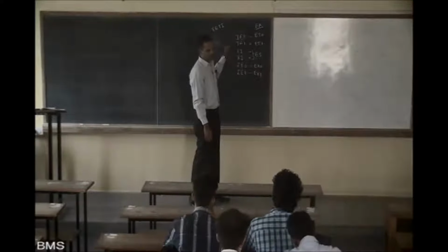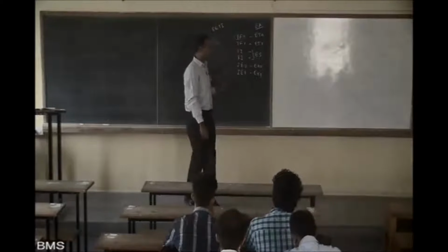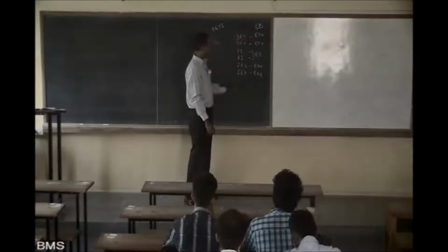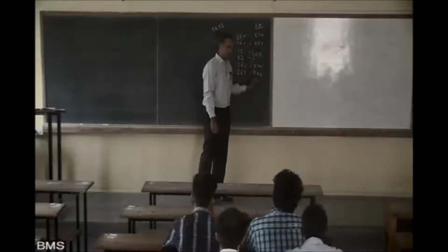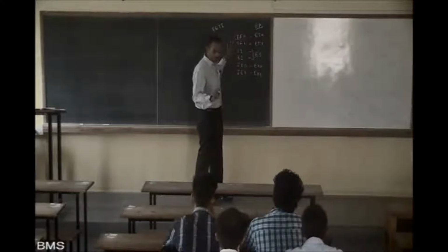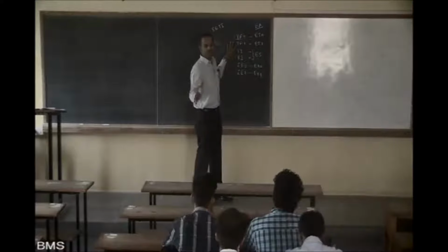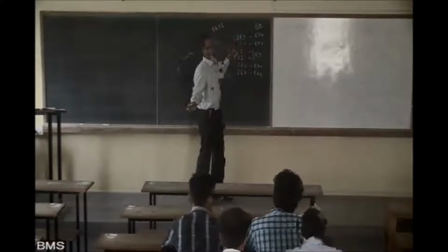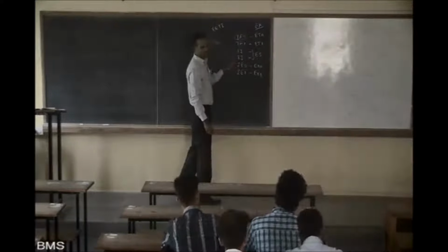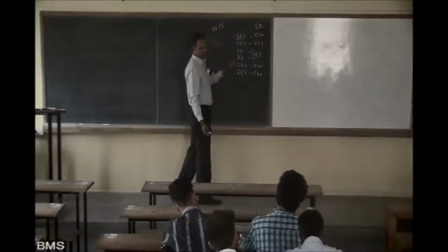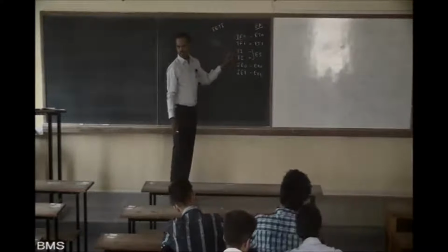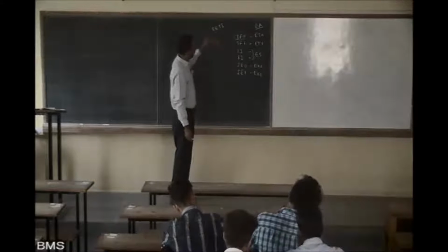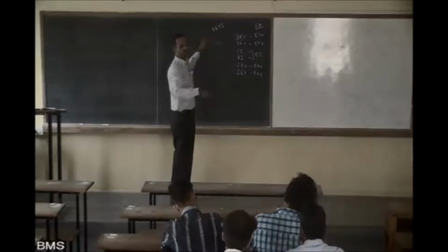Did you get it? This is a very, very basic point. I hope it is clear. These are interrupt flags. These are interrupt enable flags. They are there already in your system. The way in which you handle them is different. Using the JNB instruction for TF0. Even for TI and this we did the same, right? JNB instruction only. Same instruction. So using JNB we used to poll every time.